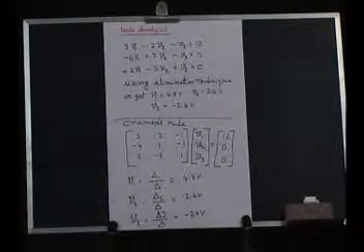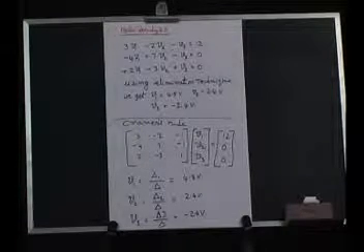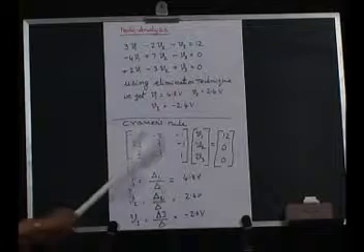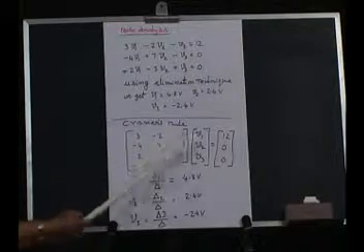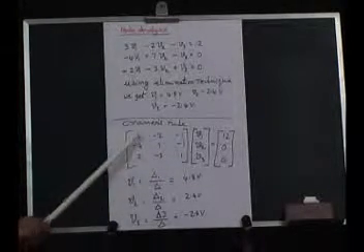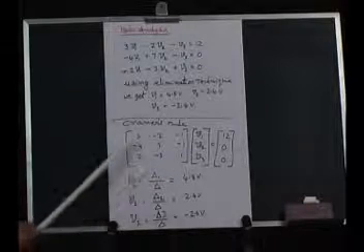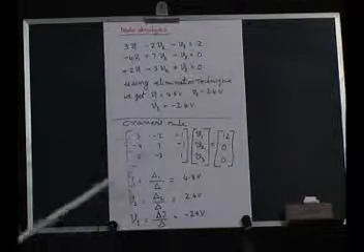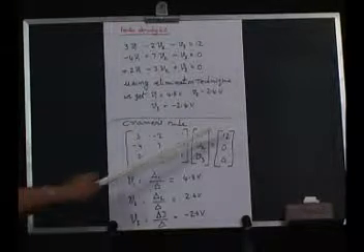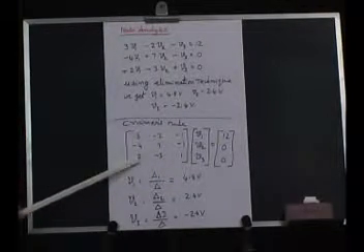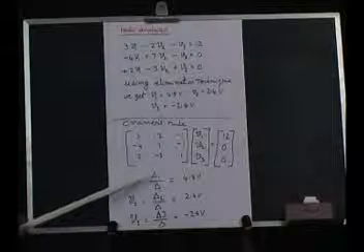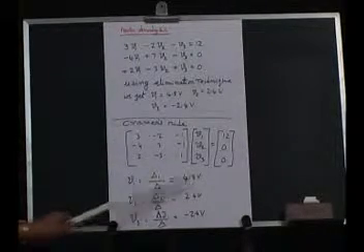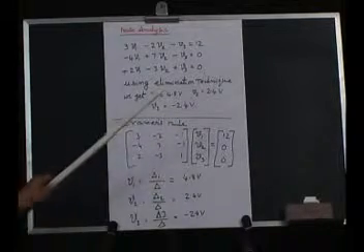In Cramer's rule, the first step is to find the determinant of the coefficient matrix. Next, we find the determinant by replacing these 3 elements with the constant matrix for V1. So, V1 is delta 1 by delta, which is equal to 4.8 volts, the same thing.